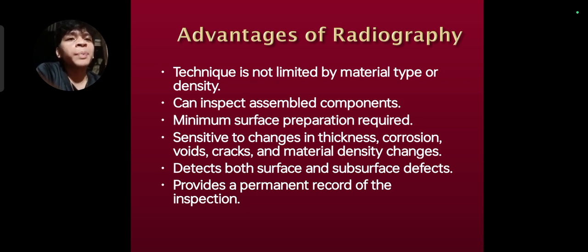It can inspect assembled components. As presented earlier, the scientific calculator is an assembled component, so we are able to see through its internal components. Minimum surface preparation is required. It is sensitive to changes in thickness, corrosion, voids, cracks, and material density changes.